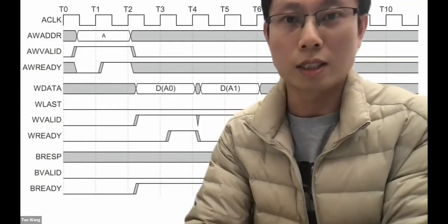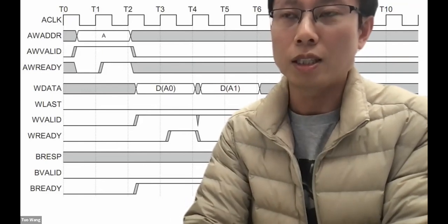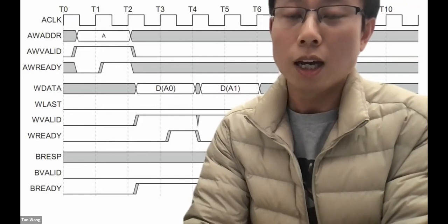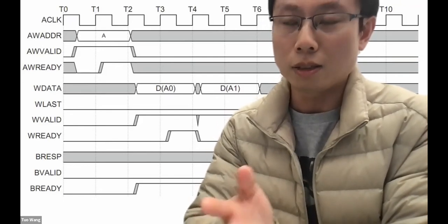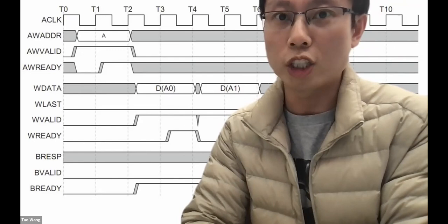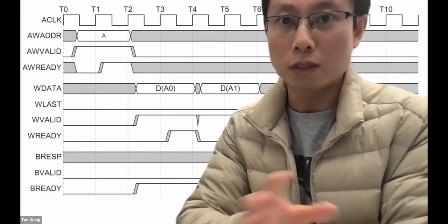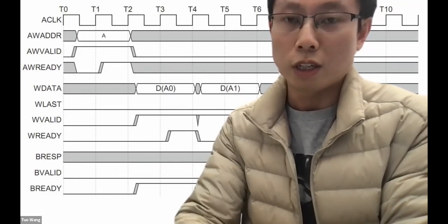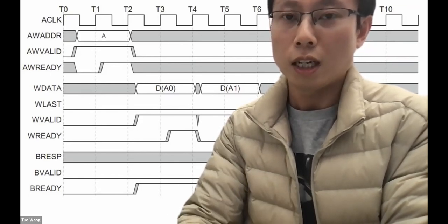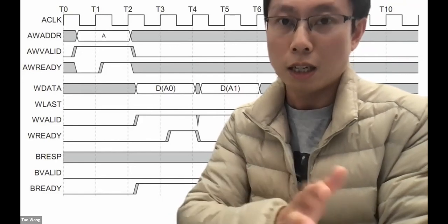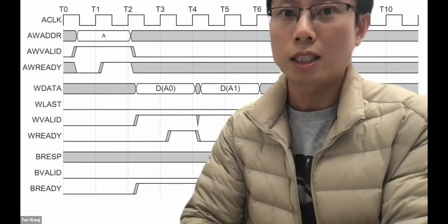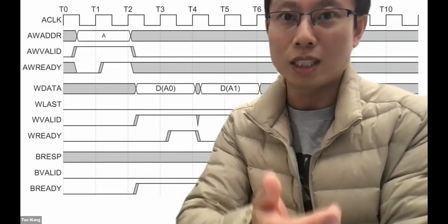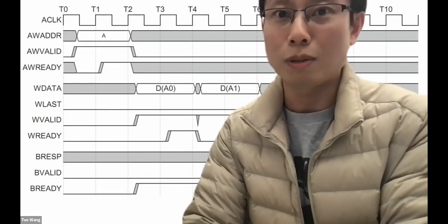CLI will take precedence at the beginning, basically because with CLI, we are not reinventing the wheel. We are taking advantage of the UVM config DB in that format. So CLI will be applied at the end of the new function. So CLI will override whatever you define or override at the beginning in the new function. But after that, if you have a further override, that further override will take effect as simulation time passes. So to answer your question, at the beginning, CLI overrides. CLI precedes; later inline overrides take precedence.